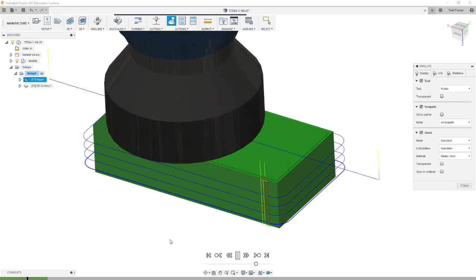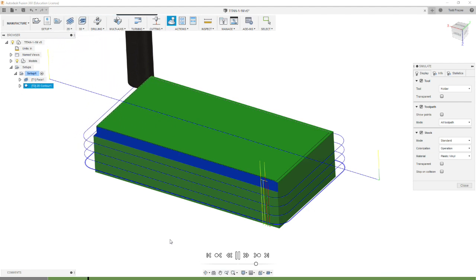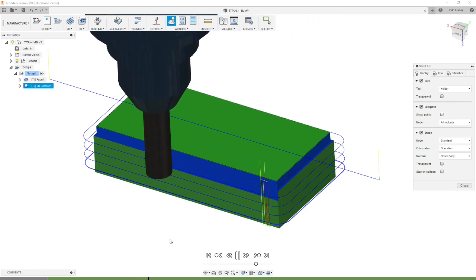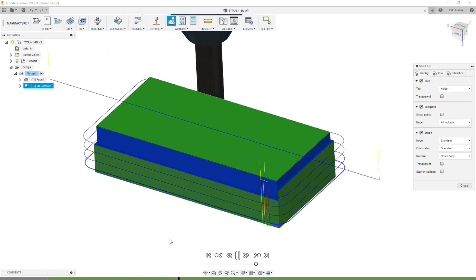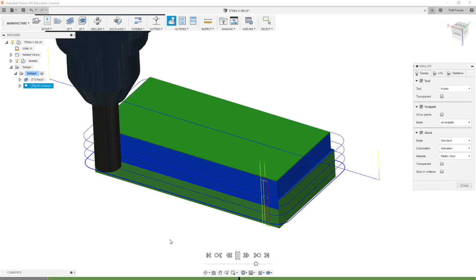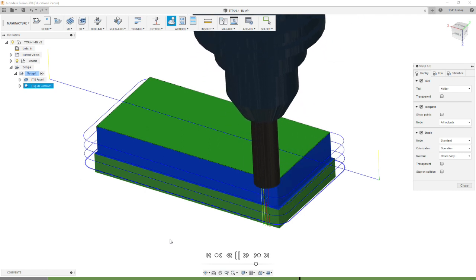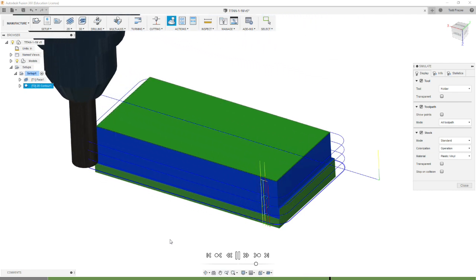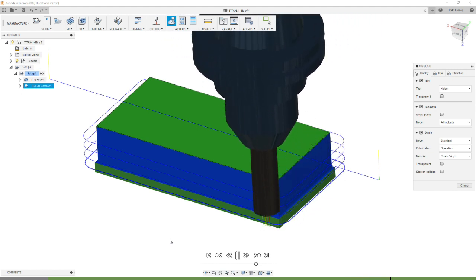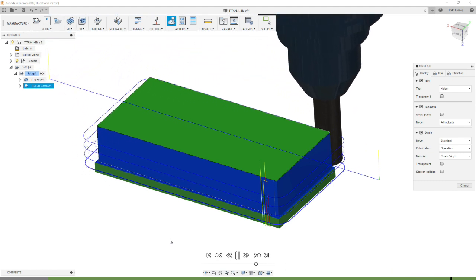You're going to see the cutter come across, mill the face, our 1/2 inch end mill comes in, machines the perimeter to size with a plus 10 thousandths for a rough cut, comes and makes another step, another step, and now it's doing a finish cut, just skimming off 10 thousandths.